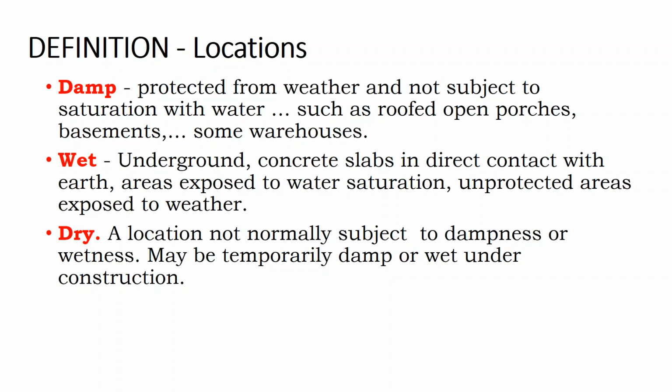And you might say, well, that's ridiculous. Why does it need listing? That UL listing is expensive. It's just driving up my project costs. Well, it might be that the thicker jacket causes the wire, when it's contained inside a conduit rather than out in free air, to heat up. And so it might have a different reaction to being enclosed in a conduit than a thinner jacketed wire.